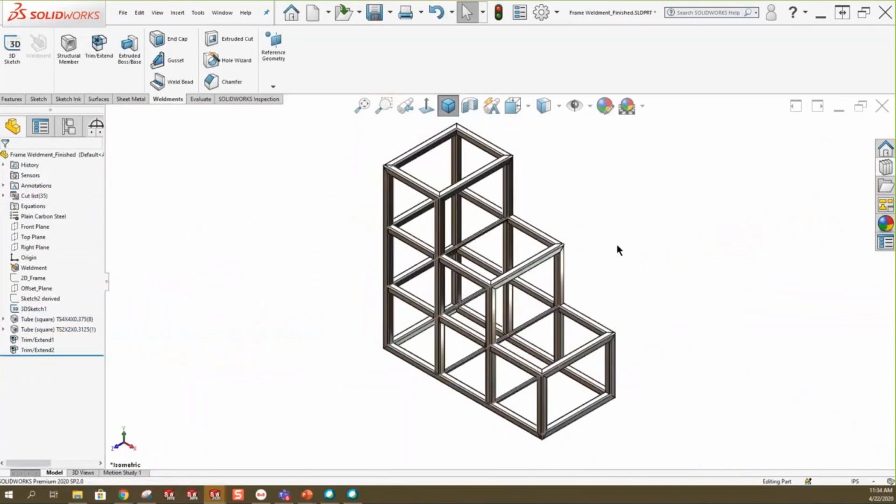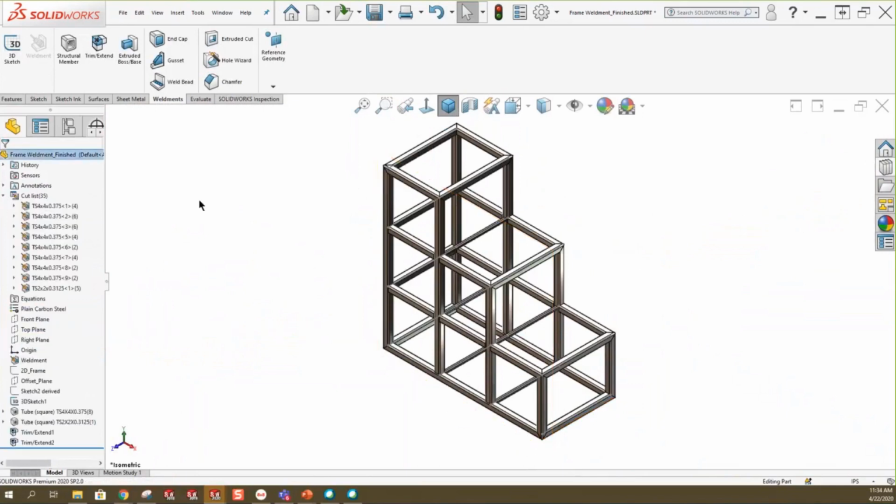All right. So now that I've got this, I want to just take a quick look at my cut list real quick. Currently, you can see I have 35 bodies, right? So there's my 35 bodies. And what they're doing is they're putting like sizes together. These have to be identical to each other, all right? Any difference in them, if I add a hole to one of those bodies, it's going to take it out of its list and say, nope, it's unique, right? Just to give you an idea on that. But you can see how it's put everything together.